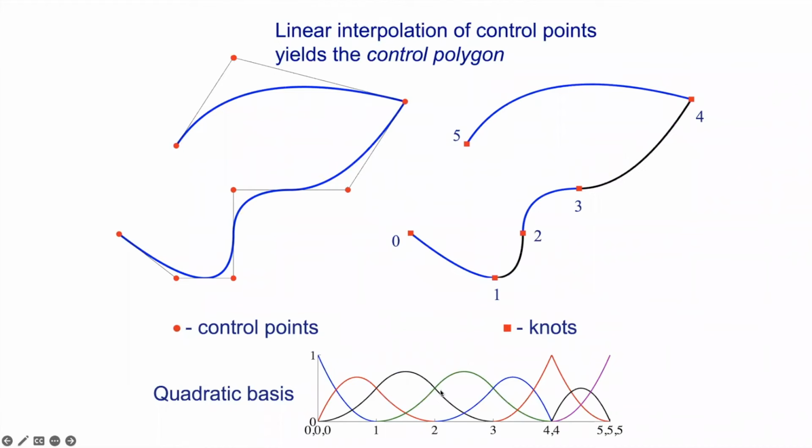If you take that basis and multiply it by coordinates, control points, you get this object. And you can see that you're in general not interpolatory, but you're smooth everywhere except for this C0 point. This is kind of the designer view. If you tug on the control point, you change the shape. But because of the properties of these functions, you will change the shape monotonically without ever introducing oscillations. And that is absolutely essential for design.